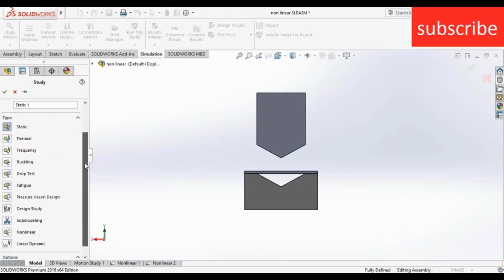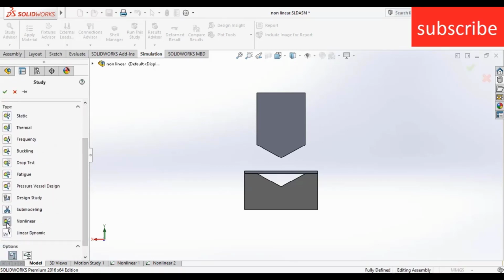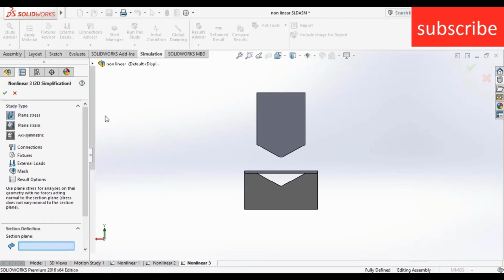Now move down the cursor, select non-linear. After that, make sure you select static and use 2D simplification. A question that will arise in your mind is why I am using 2D simplification. If I do it in 3D, it is going to take a lot of time. If I use 2D, it will reduce the time because it's just 2D geometry and it will show me a good result in less time. So make sure you select 2D simplification, click OK.